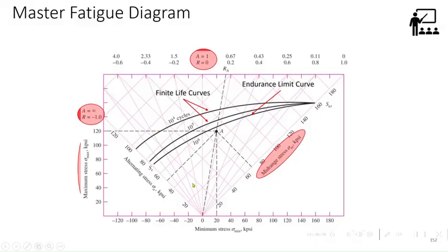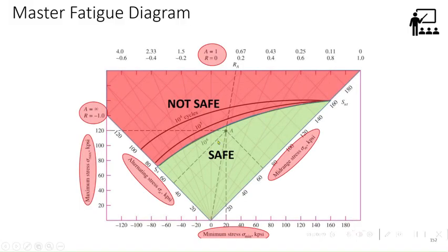The idea is that if you have some indication of stress amplitude or S max or stress, any one of them known, two parameters out of three you should know. In that case, if the curve is there, this being the material property, quickly you will be able to come to a conclusion about what the life should be. Of course you need to apply some factors, this is again material property, and after that you can have a scatter factor, but one can quickly get an answer. So as long as any combination of stress amplitude and so on is less than the 10 to the power 6 endurance limit, this is for ferrous material, that's why you have a very safe infinite life.